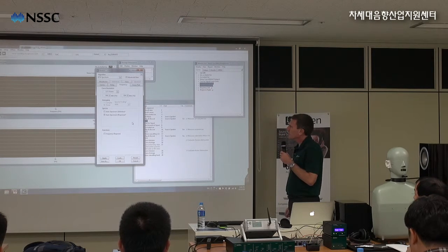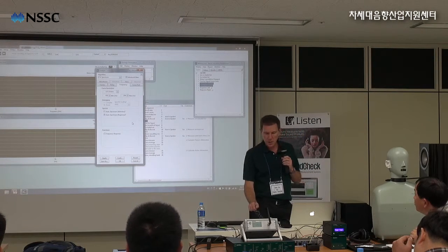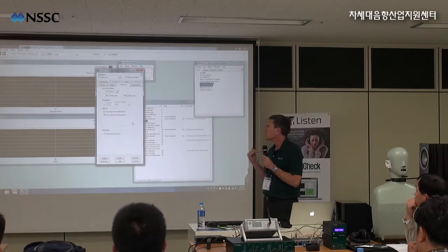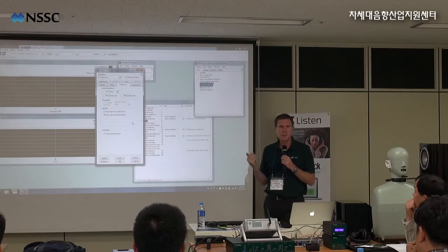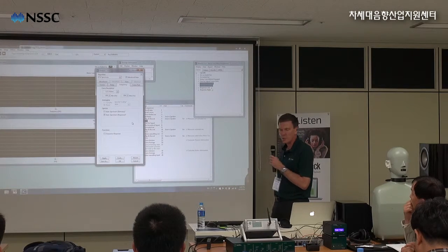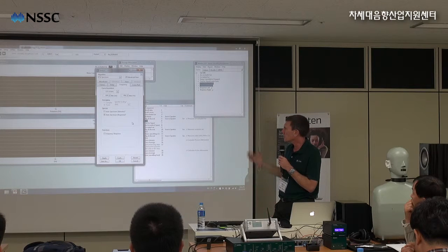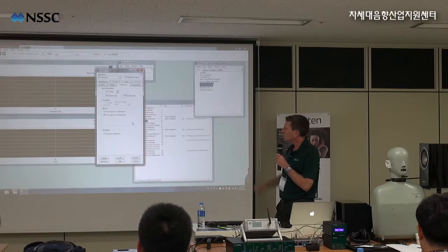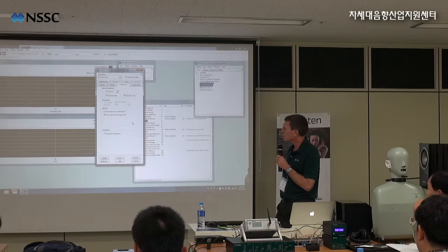You can do it in whatever resolution you want, but typically when you see specifications, they'll do it in so many nth octaves. I guess if it were me, I'd probably do 12th octave, but this is typical of the standards, 3rd octave. And in this particular case, 100 to 10 kilohertz is the range we're going to look at.